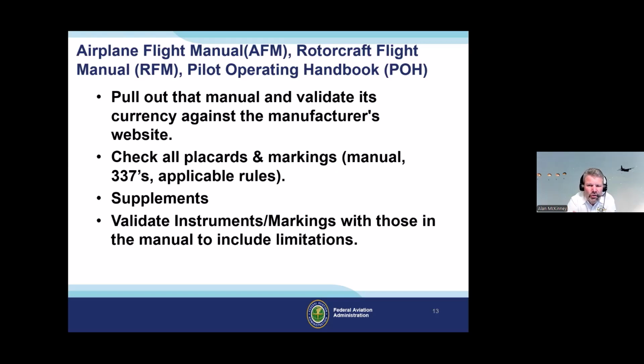So if you go to the manufacturer's website and print out the current flight manual, and the extend gear process or emergency procedures all cover the hydraulic stuff, and yours is the old bike chain, while it might be the most current on the website, it's not really current for yours. Current, by legal interpretation from the FAA, was current at the time.